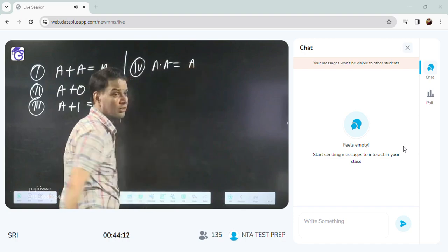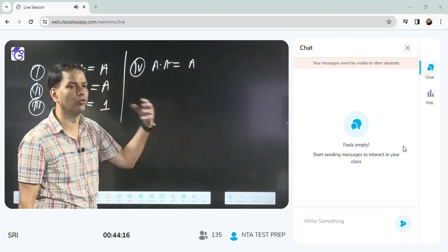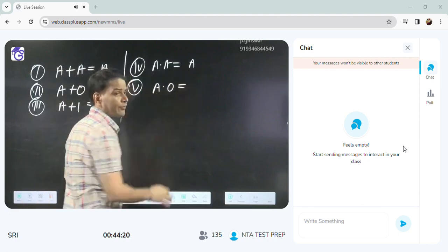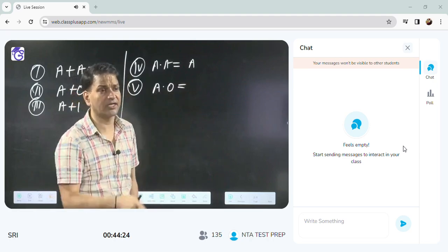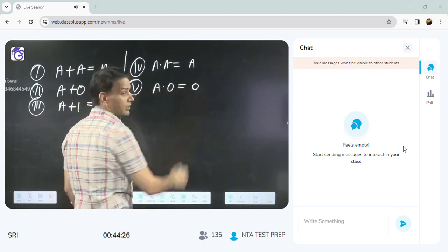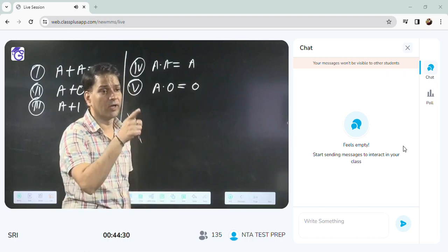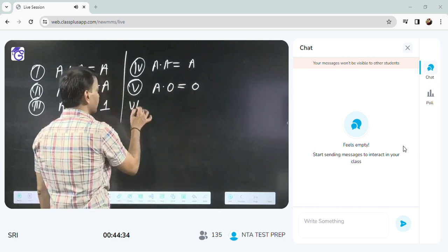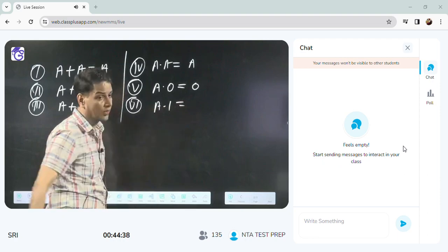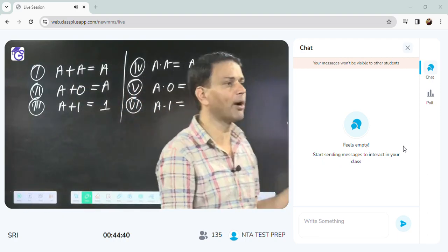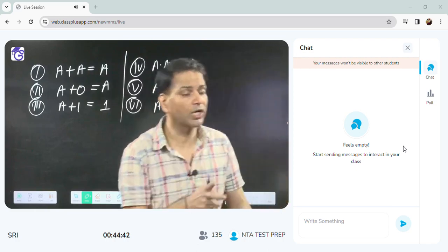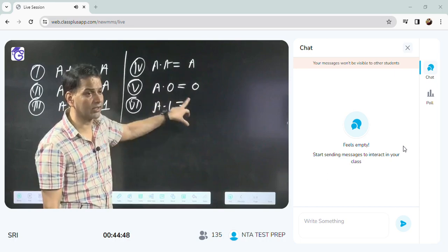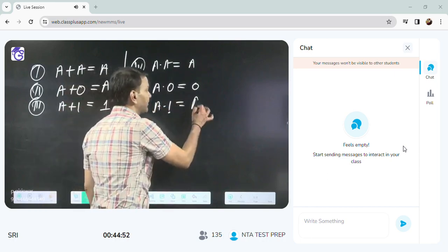Okay. Then A dot A. A dot A is also A. True and true, then it will be true. False and false, then it will be false. Okay. Number 5, A dot 0. If any one is 0 in the case of AND, then what will we get? 0. Because we get 1 only when both are 1. If any one is 0, the output is 0 in the AND operation. 6th one, A dot 1. 1 is 1, but I don't know about A. Only one case I will get 1, when both are 1. Here they have given 1, but I don't know about A. If A is 1, then I will get 1. If A is 0, then I will get 0. So it means it depends on A.